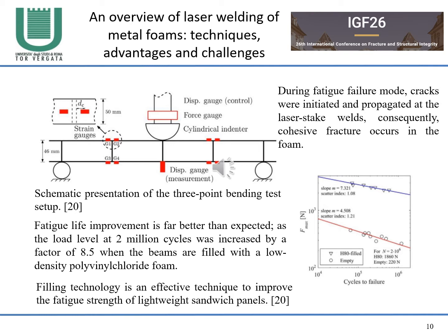Fatigue life improvement is far better than expected, as the load level at 2 million cycles was increased by a factor of 8.5 when the beams are filled with a low-density polyvinyl chloride foam. Filling technology is an effective technique to improve the fatigue strength of lightweight sandwich panels.